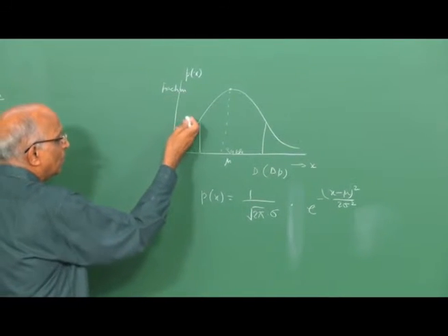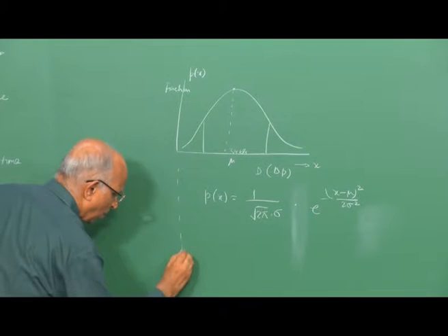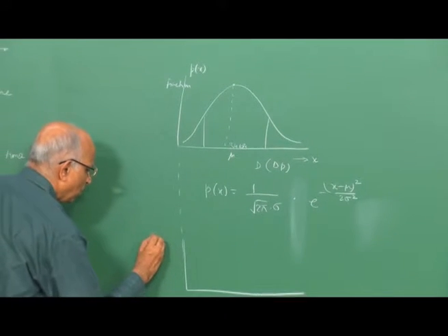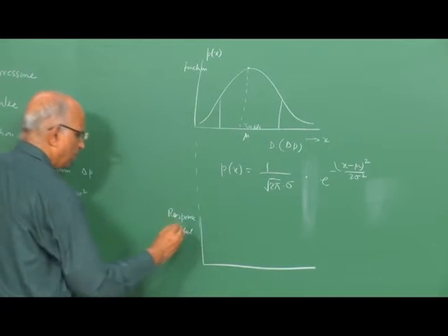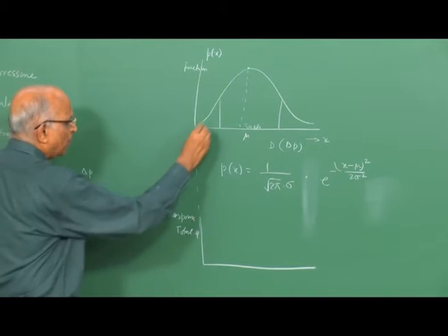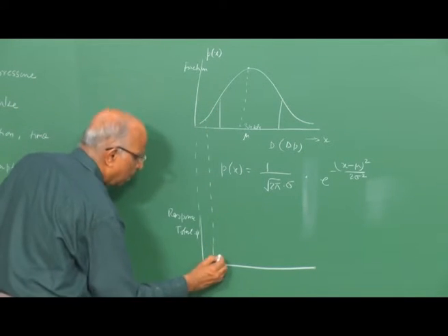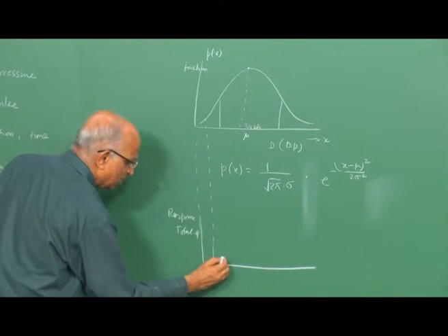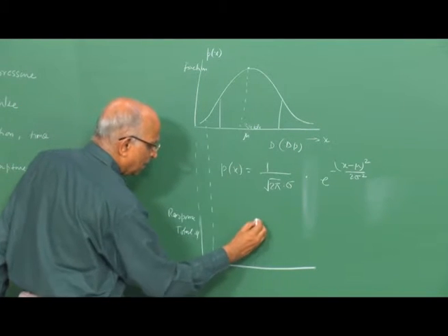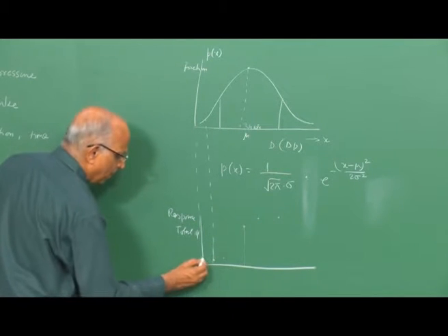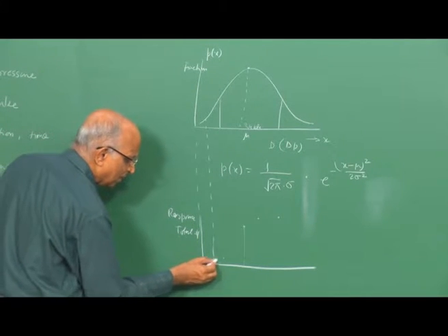If I am going to take a look at the total response or the total number of people who are affected, then I again replot this figure over here. I am now talking of the response, or rather the total number of people who are getting affected. Well, for this low level of overpressure, a small number of people get affected. At this value, some more get affected, this plus this much gets affected. For the mean, some more people get affected. And now the increment gets smaller, and therefore, the total response, or the total number of people who are getting affected, goes as maybe something like this.